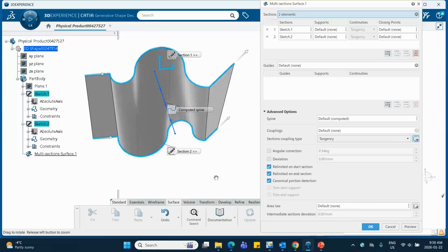Okay, now, if you change this thing to tangency, then curvature, that means first connect the points that the tangent are discontinuous, and then go and figure out where are the curvatures discontinuous and connect them. So if I select this and say apply, notice that right now there is no line, visible line.